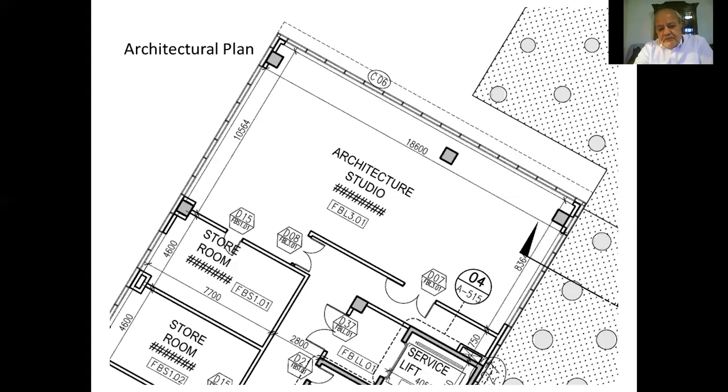So the first stage is that we start to indicate the location of the center lines, the location of the structural systems, columns, shear walls, everything that is structural. We have to indicate it. And we have to develop our building envelope system.